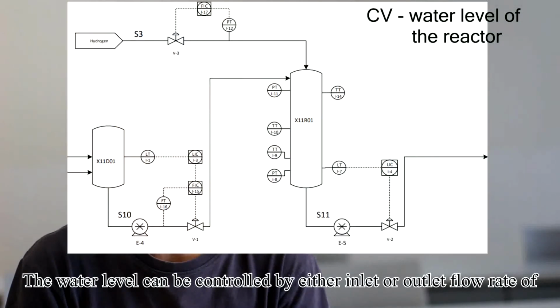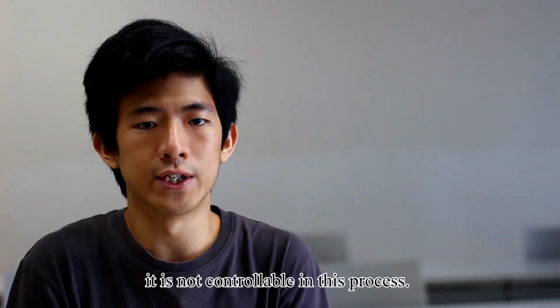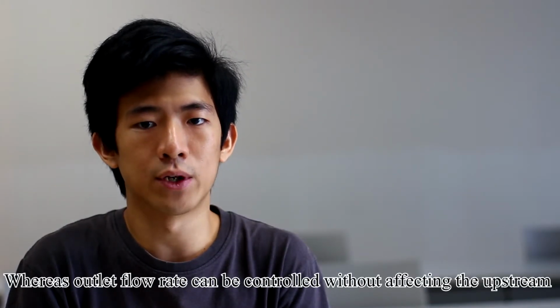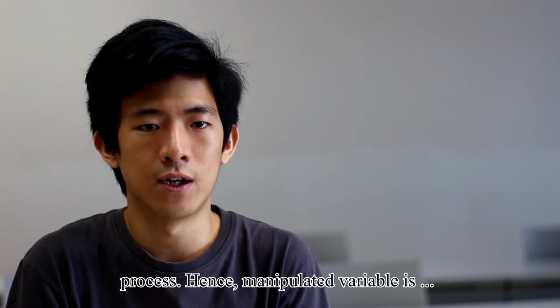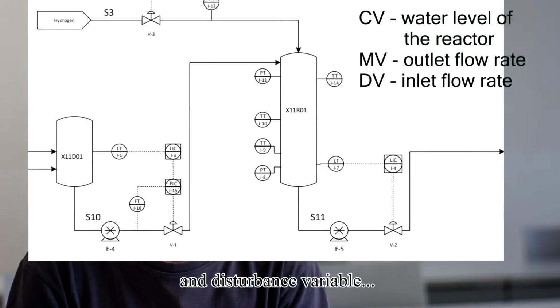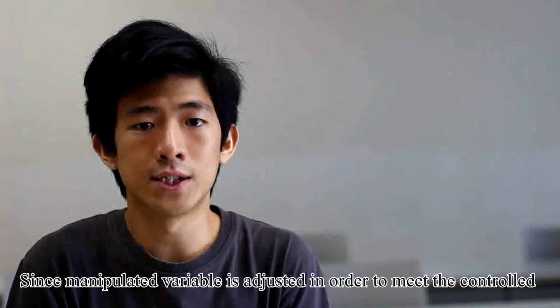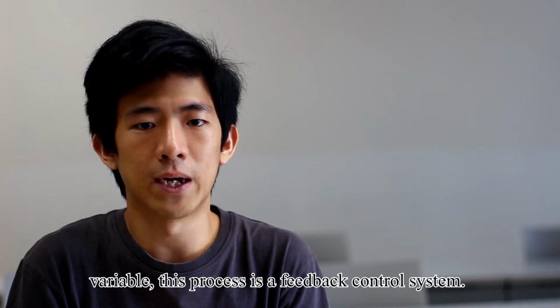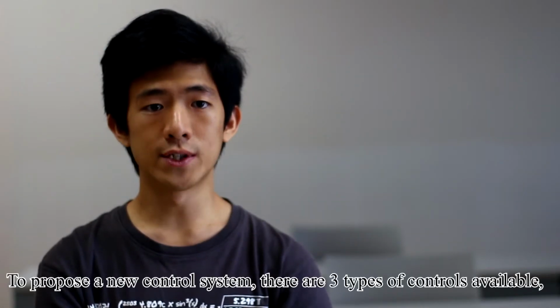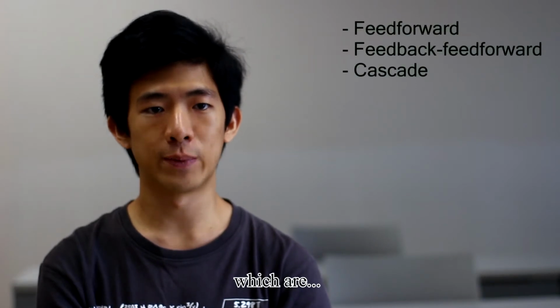The water level can be controlled by either the inlet or outlet flow rate of the reactor. However, the inlet stream is dependent on the upstream process. It is not controllable in this process, whereas the outlet flow rate can be controlled without affecting the upstream process. Hence, the manipulated variable is the outlet flow rate of product, and the disturbance variable in this process is the inlet flow rate of the reactant. Since the manipulated variable is adjusted in order to meet the control variable, this is a feedback control system.